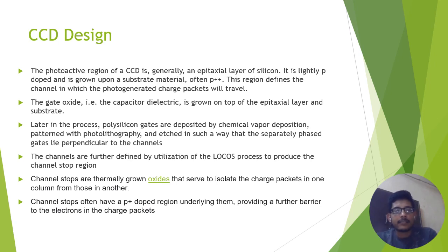The design of the CCD sensor is like this. The photoactive region of a CCD is generally an epitaxial layer of silicon. It is lightly p-doped and grown upon a substrate material of p++ material. This region defines the channel in which the photo-generated charge packet will travel.